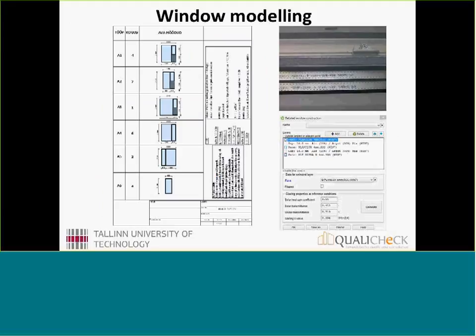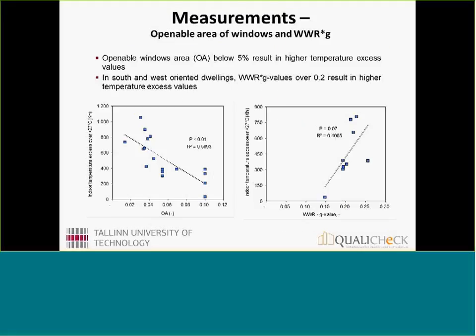And indeed, it is also very important to specify correct window parameters in the simulation, because they have a very strong effect on results. Now I am showing some results. These are actually from the measurements, and the last graph shows a nice correlation between excess hours and openable window area.